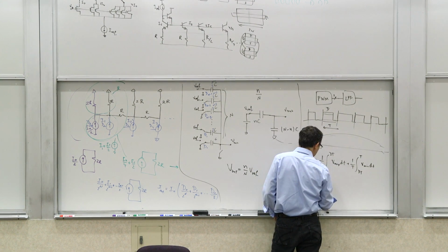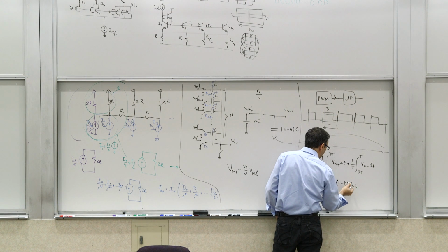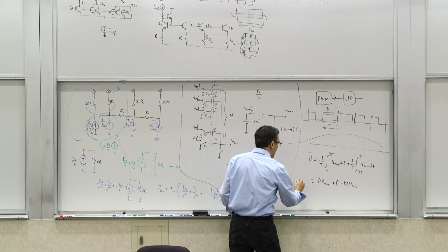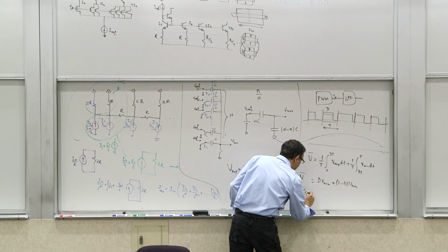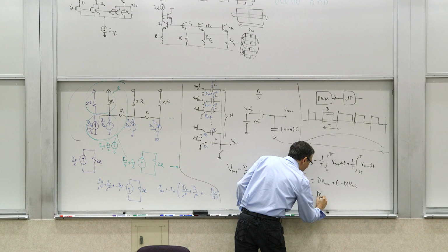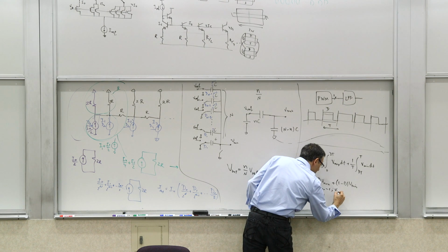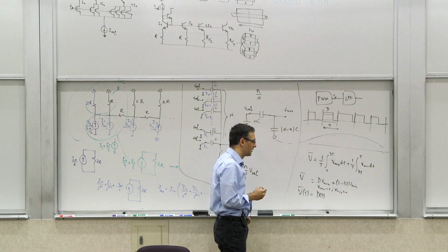You get d V max plus (1 minus d) V min. And if your V min and V max are 1 and 0, you can produce something where your slowly varying average, so now I'm making that a function of time, can be determined simply by the duty cycle. So let's say V max is 1 and V min is 0. So it becomes basically that.